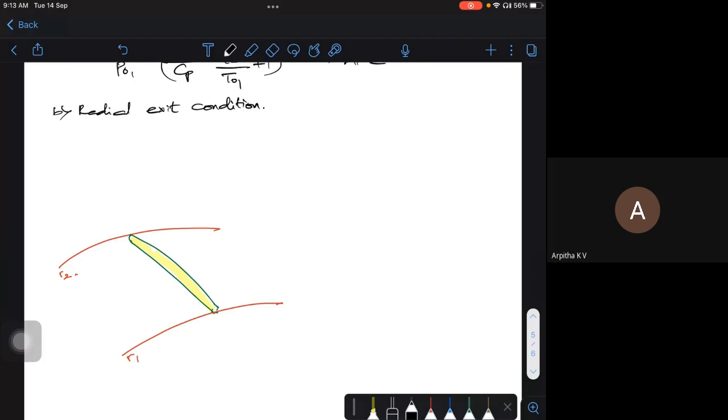So along the blade, I will be having what is called a relative velocity. If I draw the velocity triangle, along the blade I can write my VR2. Then in the flow direction, I'll have the VF2 at the exit. Then you have your absolute velocity in this direction, V2. Everything is covered, so I can close it. This is my triangle.